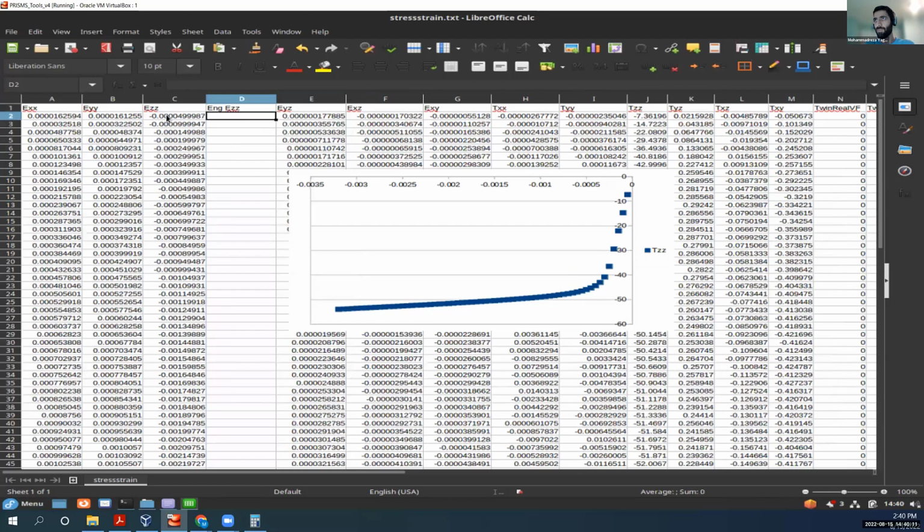And I know I'm applying 0.0005 minus for each increment. And then I will add this minus 0.00005. So this number, you can see it's very close to the Green strain tensor for small strains, but then it's going to deviate from that eventually.